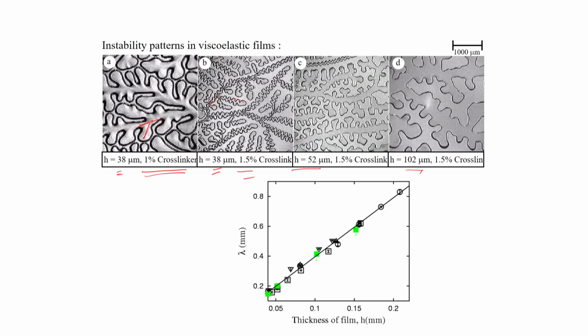In other experiments people have seen such finger-like structures. These are signature of viscous instability, which is also known as Saffman-Taylor instability. I am not going to go into that. Over here we have these fingers which appear normal to this main axis. See, this is the main axis of the finger, and these side fingers appear normal to the axis. Then we can measure the wavelength, the distance between these fingers, over the whole image, and we can obtain the wavelength.